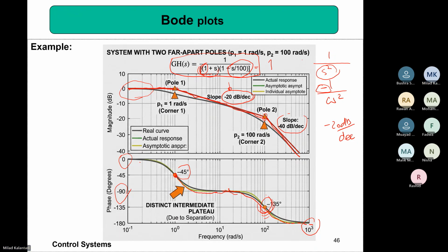And we call it phase margin. So for this case, the phase margin is what? The phase margin is 180 minus 0 degrees. We always compare with 180 degrees. It means that it has 180 degrees of phase margin to become unstable, right?